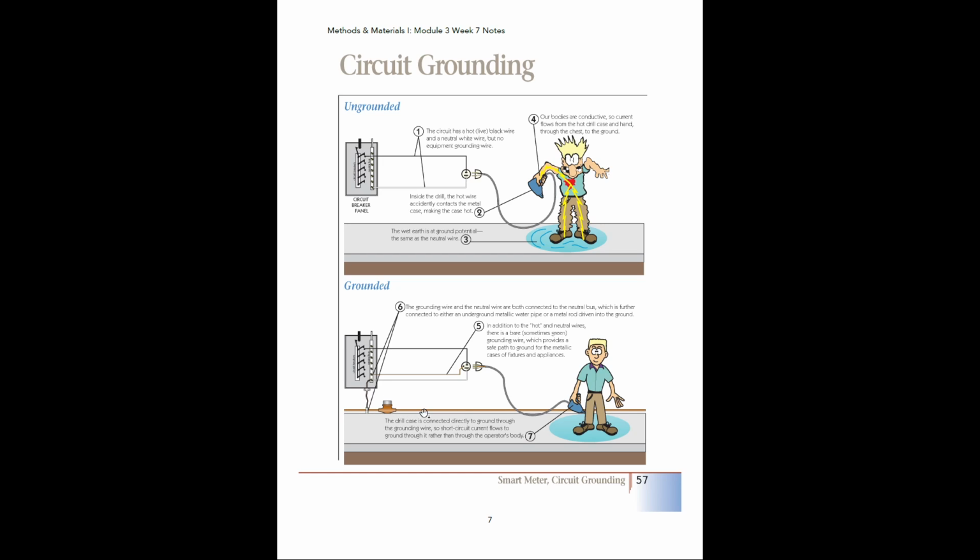All right, so this pipe here is an example of the main water line that's running through the house. Usually that's going to be made of copper or some kind of metal, okay? The wire is going to be tied to it, and that is naturally going to discharge it to the earth. So basically the ground wires are there to prevent these accidents from happening, to prevent people from being electrocuted, because they are the thing that attracts the electrical energy instead of your body, okay?